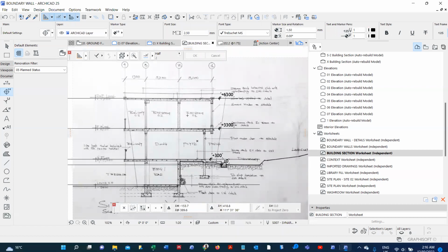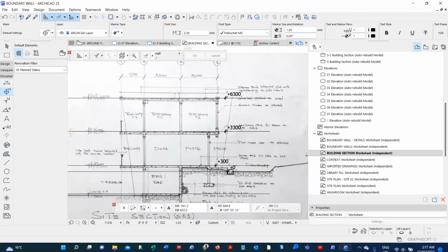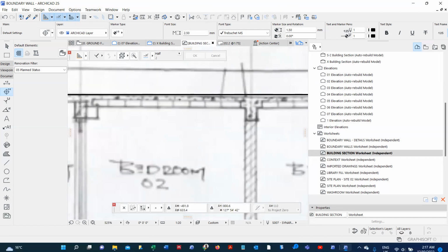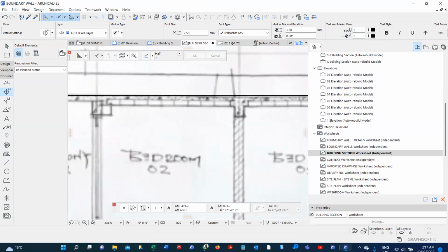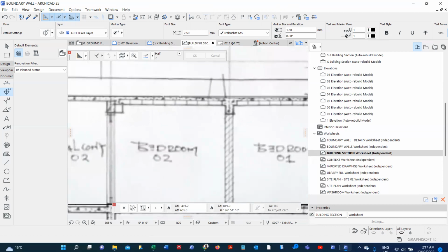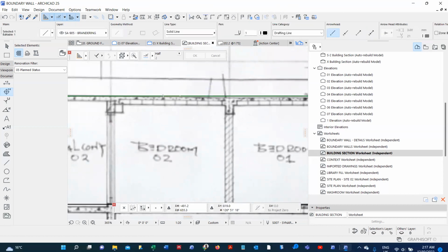We also need to identify the depth of our beams and the depth of our slabs. Now, in this context, the student has deliberately used hollow pot. And for the hollow pot, we can give it a depth of 300. And then for the beam, we can also give it a depth of another 300, so total will be 600.